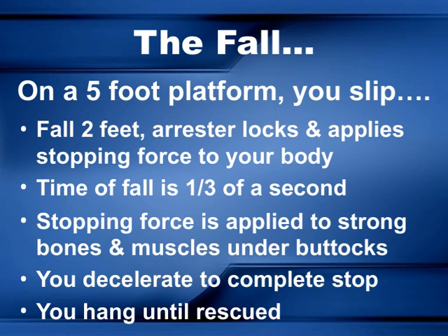During that brief moment, the arrestor system works to decelerate you rapidly. Most of this stopping force is transferred to the strong bones and muscles underneath your buttocks, which are designed to handle significant loads. As a result, you slow down and come to a complete stop. Once stopped, you might find yourself hanging there until someone comes to rescue you. This fall process highlights the importance of proper fall protection systems. They're designed to control the fall, limit injury, and keep you safe during these critical moments.